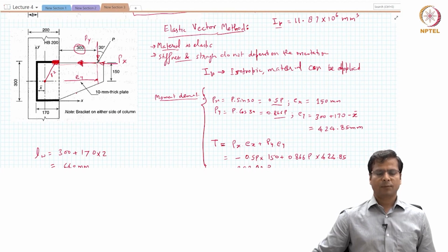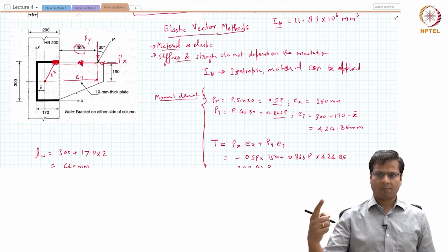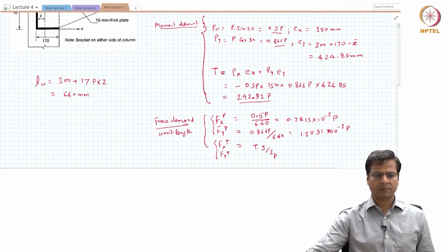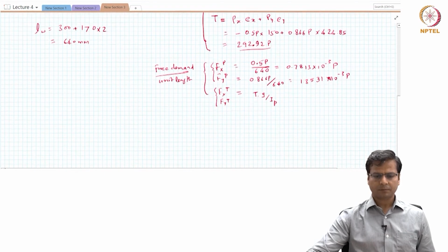The reason for that is, first, the force for a given rotation in that segment will be proportional to the distance, right? And in addition to that, the moment because of that force will again be proportional to the distance. So because of that, this distance comes twice in the equation.